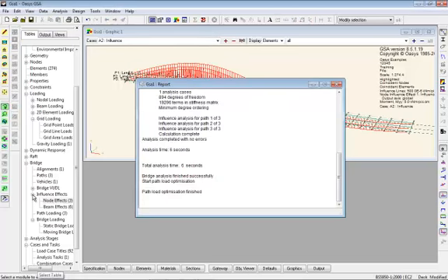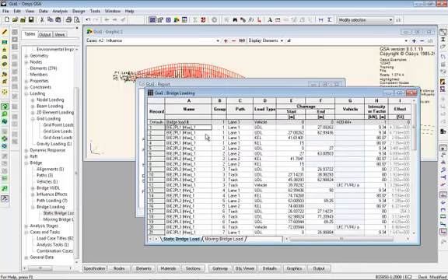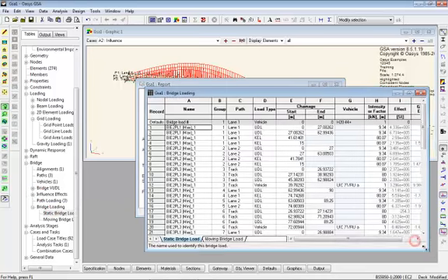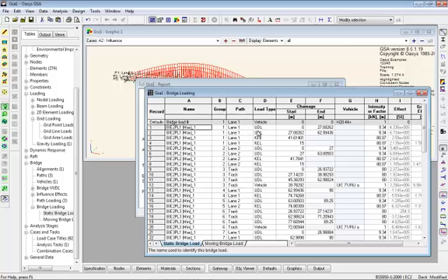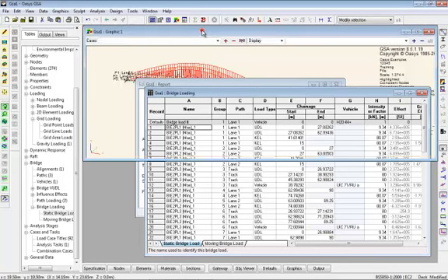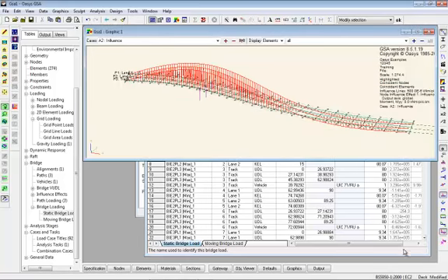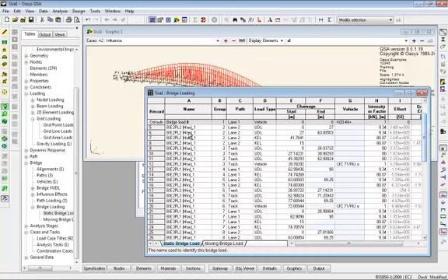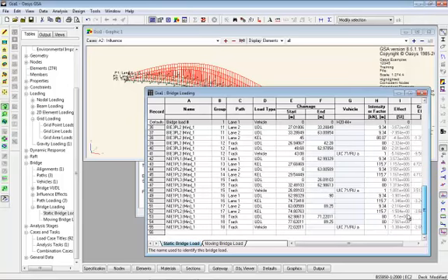And this creates a whole series of static bridge loads, various UDLs and knife edges and so on at various chainages and widths and so on. And the bridge name is a code to say what that load is expected to do.